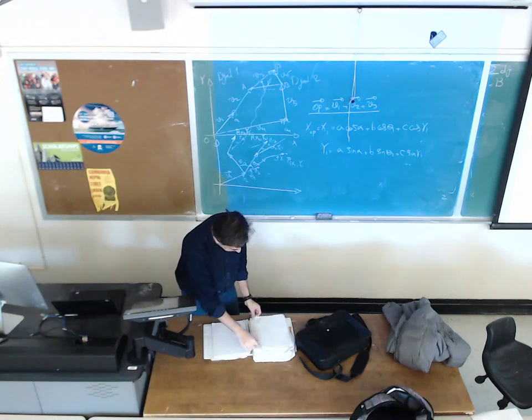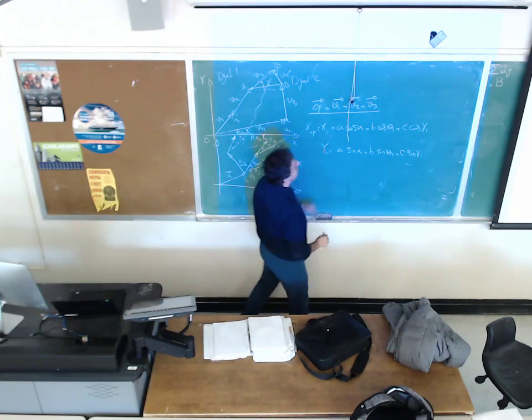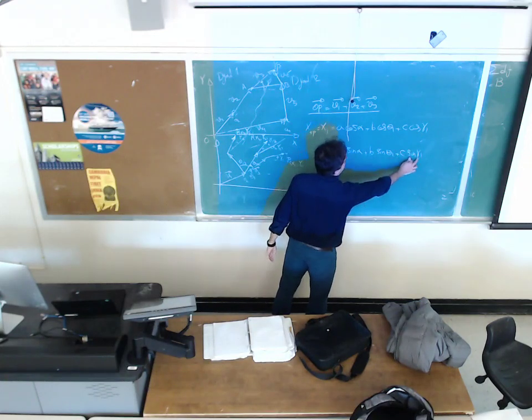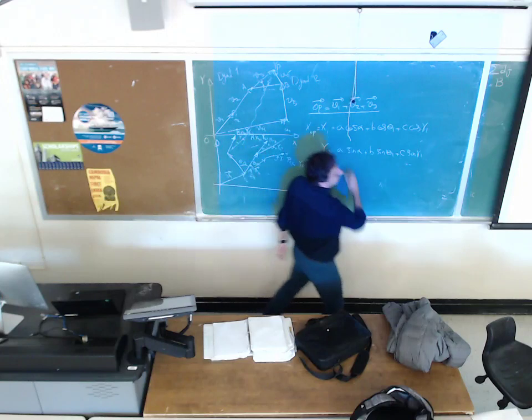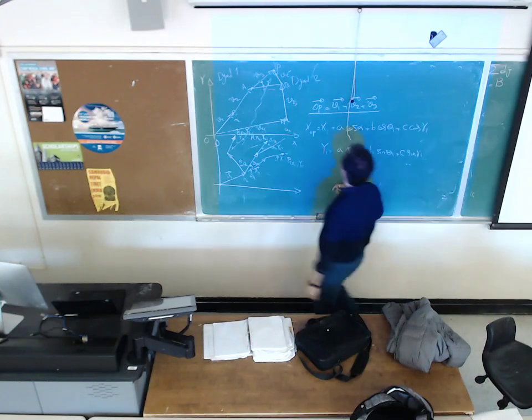So we have 3 precision points. So this equation can be written for theta 2, gamma 2. Alpha is not changing because, as you see, when the mechanism is moving, this vector is fixed because joint O2 is not rotating. It's not moving. So we are going to have 6 equations.